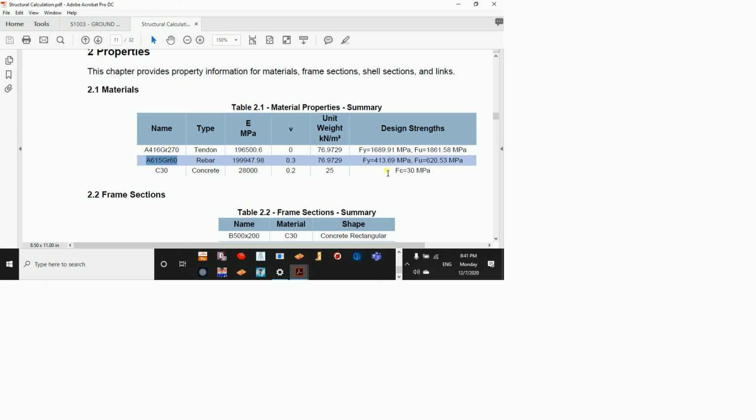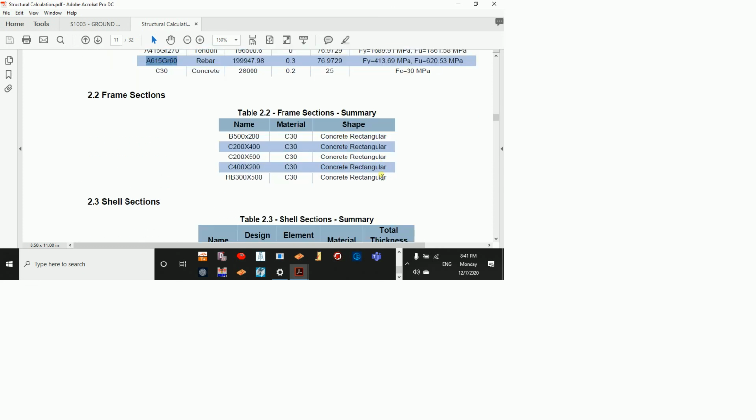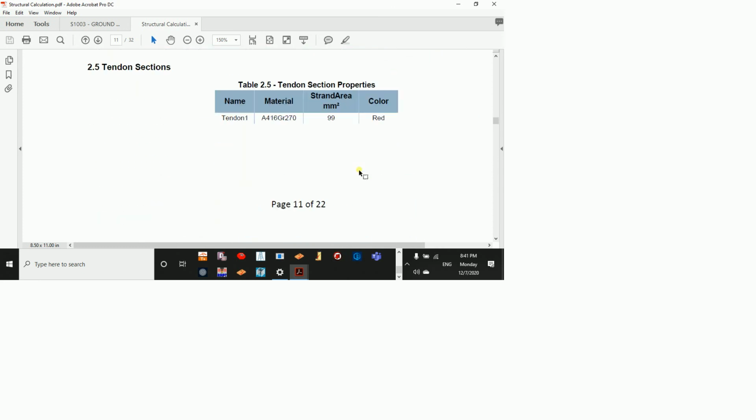It means instead of using the full strength of the steel, he has reduced the steel, which means that you require more steel. So when it comes to ETABS, since a lot of things are not available, you need to be careful. For example, instead of 5 bars, he's supplying 6 bars.